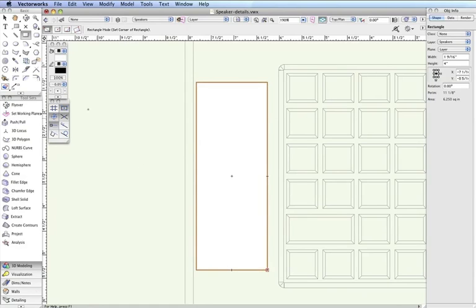Now select the Circle tool from the Basic palette, and be sure the first mode, Circle by Radius mode, is enabled. Click anywhere inside the newly created rectangle to start drawing the circle. Press the Tab key to enter the length field and input 1/16 of an inch. Then press the Enter key to lock in the value. Now click anywhere in the drawing to place the circle.